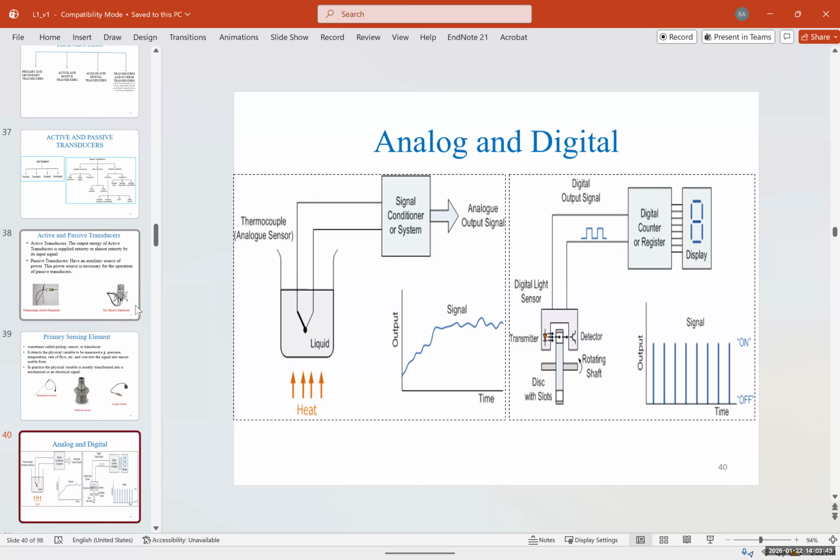Now, you are all familiar with analog and digital signals. You see an analog example on the left. It's continuous, and then you have a digital. Digital means a digit-based or discrete signal. The reason that the majority of the processing that we do is on digital is because it's much easier to process digital signals. You can easily manipulate the signal and get rid of the noise. Noise extraction is very easy. Compression of the data is easy in digital.